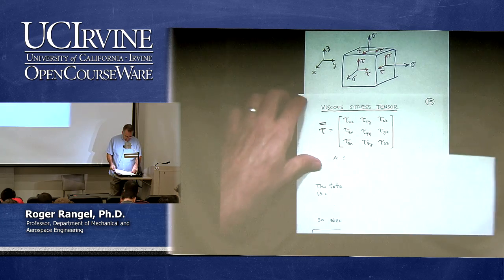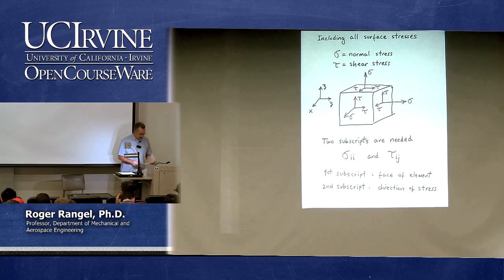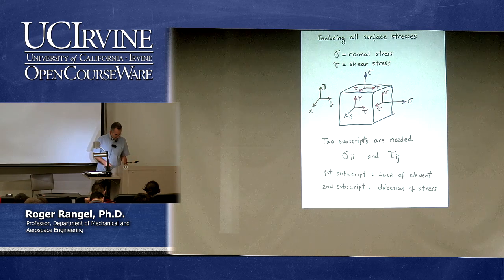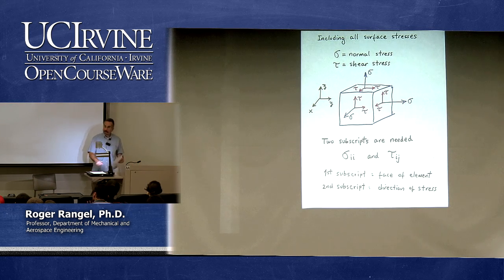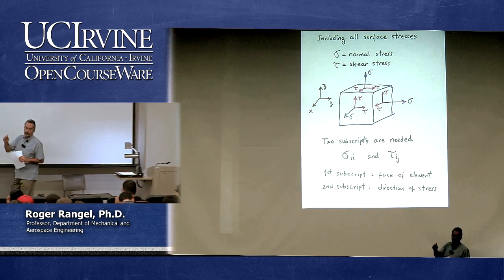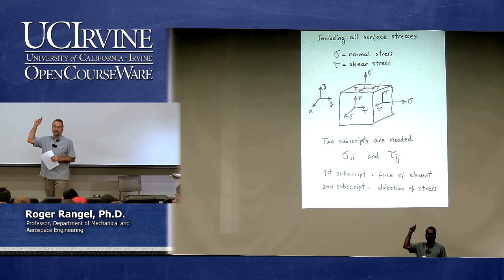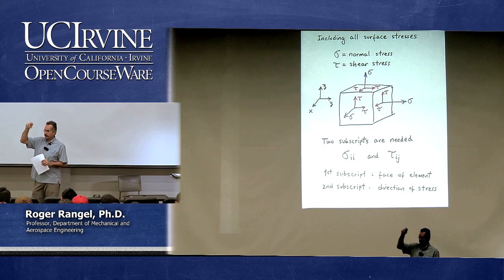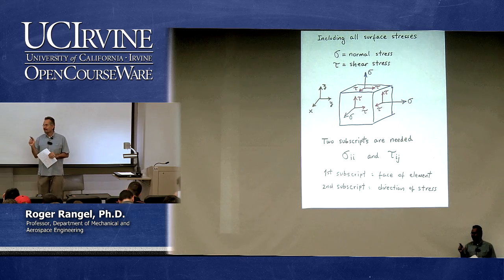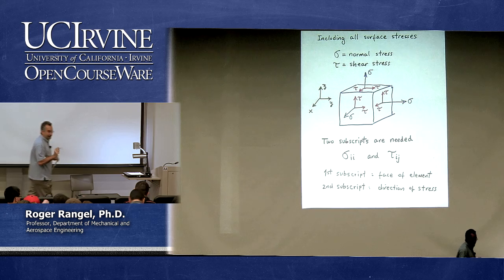All right, so now let's do the following. With that stress field, how could I find the force that is acting on my element? Suppose with that distribution of stresses on the surface of the element, can I determine the forces? Of course, the forces would be something like the stresses times the area on which it is acting. But the force is a vector, so there is a component of the force in x, another in y, another in z. And we have to separate them out.